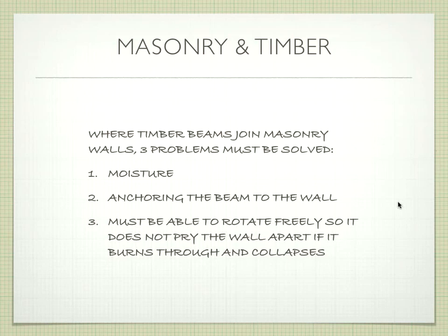Okay? We also have to deal with how we fasten the beam to the wall so that it stays where it needs to be. That's a problem. Okay? And we also need this last condition. We need it to be able to rotate out freely so that if the beam fails, right, due to fire or something like that, it won't collapse the wall above.